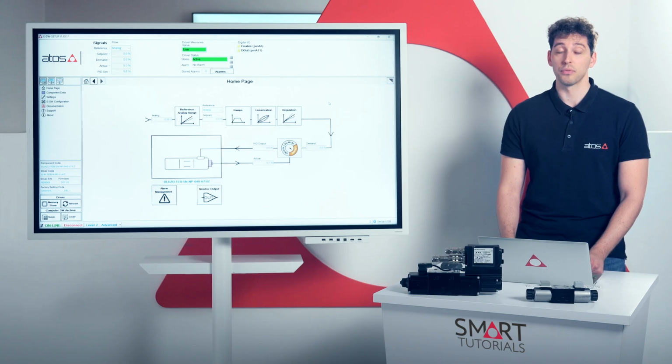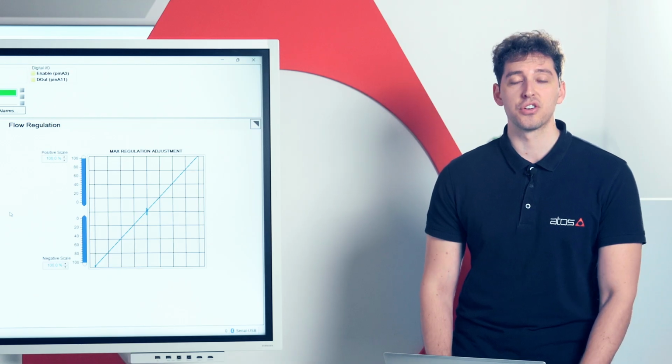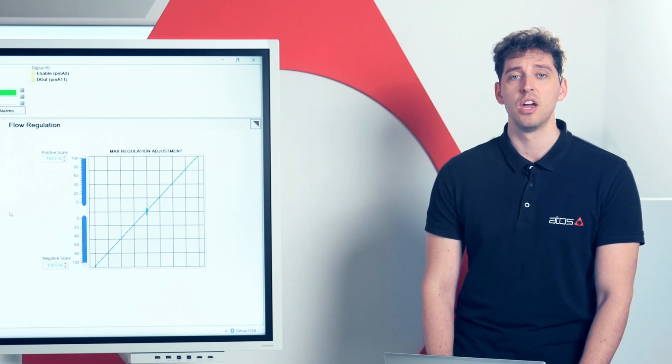To calibrate the offset with the set point at 0%, you have to adjust the offset value until the actuator stops drifting. This fine-tuning aligns the hydraulic forces compensating for the cylinder asymmetry. Scale function here works the same way we just saw for positive overlap valves.